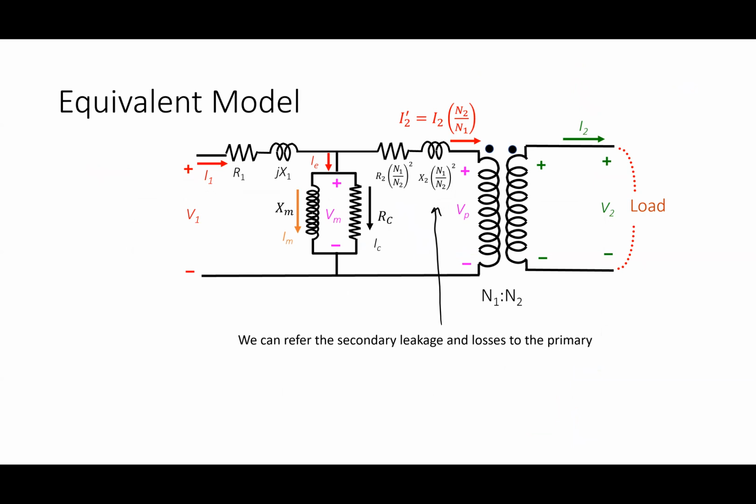This is the equivalent model that I went to last time. This is summarized in that transformer applications. If I have an impedance over here on the load side, I can reflect that over to the secondary by multiplying it by the turns ratio squared, like that. It is not hard to prove that I can move those over there. I did a little bit of a proof of it last time. But that leads to this thing here, which is sometimes called the T model, right? Because it looks like a T. If you forget the ideal transformer hanging off of it, it looks like a T.